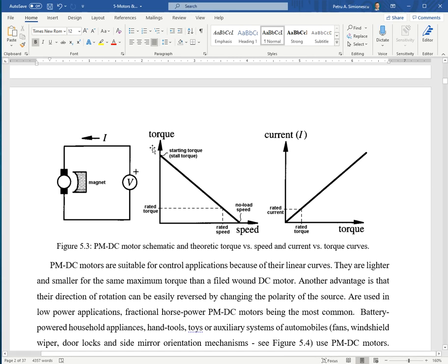So at the end, in order to provide the maximum tightness to the wood screw, instinctively you sense the twist at your hand at its maximum when you squeeze and release the trigger. So by doing so, you operate the motor around the stall torque, which is a maximum.